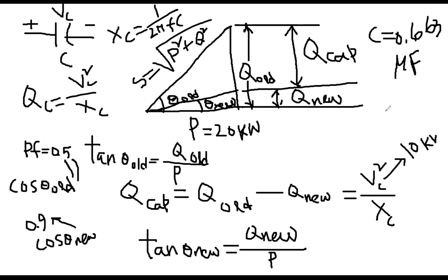Sindhuja, could you follow me? Yes, Dr. I think you easily understand this triangle. So once you see a power factor improvement problem, please use this triangle. Remember, this is called the power triangle. Just with the help of geometry, you can solve the problem. Just remember this. So everybody make sure that finally you are getting a capacitor value of 0.663 microfarad.